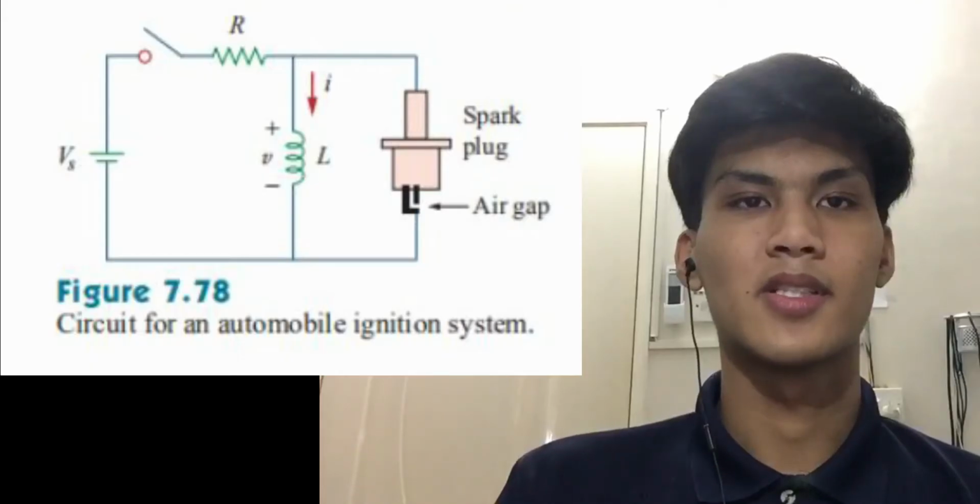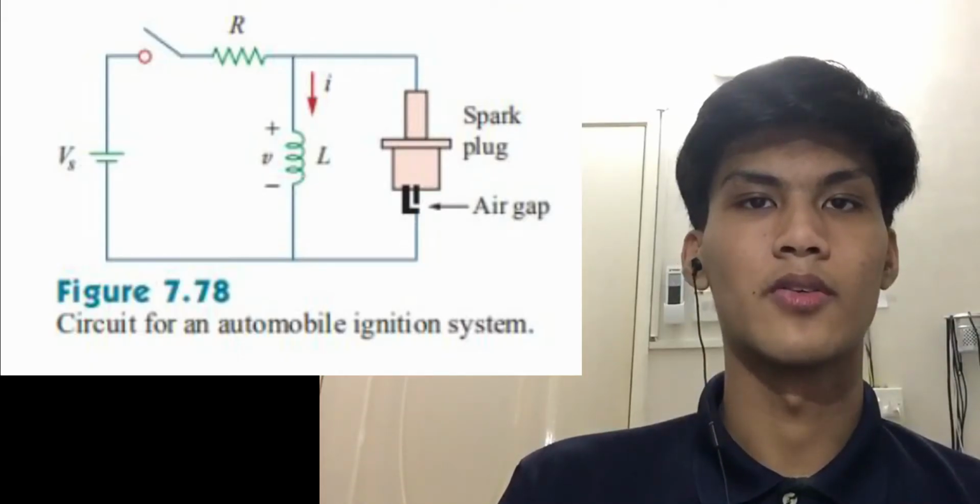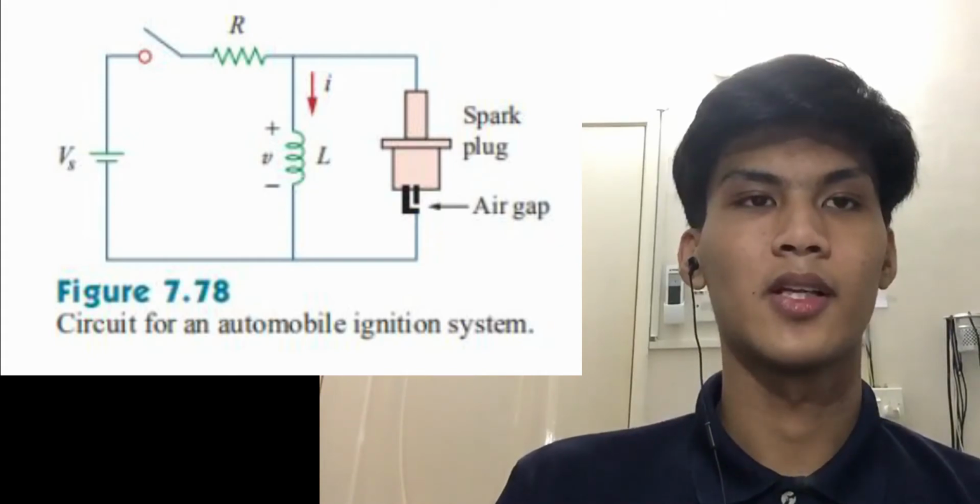When a current passes through a coil of wire wound around a soft iron core, a magnetic field is produced. In the ignition coil, a few hundred turns of relatively heavy wire are wound around an iron core. This becomes the primary coil of the transformer. Thousands of turns are wound over the primary coil with much finer wire. This becomes the secondary of the coil. There will be more resistance in the secondary coil than the primary coil because it contains so much more wire.